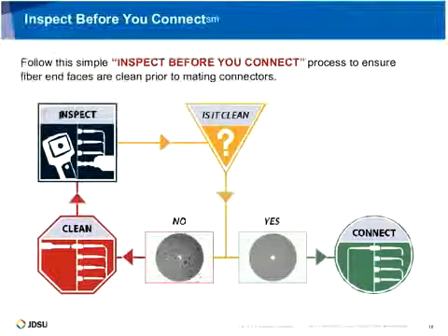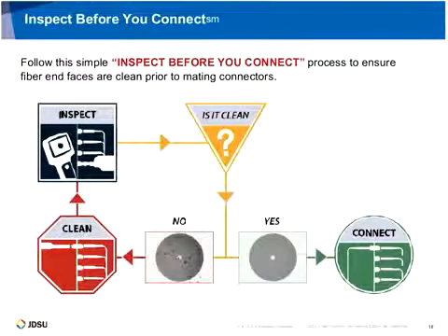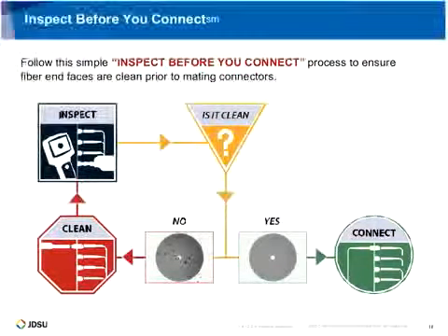The reason I say that is because there's a mentality in the industry that people think, well, I just need to clean them. I need to clean them. You'll hear that term a lot. You know, make sure that you're cleaning your connectors. And that is very true. Part of the inspect before you connect process does include cleaning if it's necessary. But it's sort of like if you're not looking at the connector, if you don't know what you have on the end face, then you're sort of flying blind.